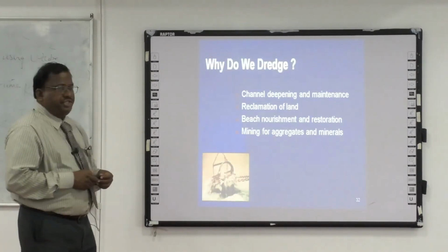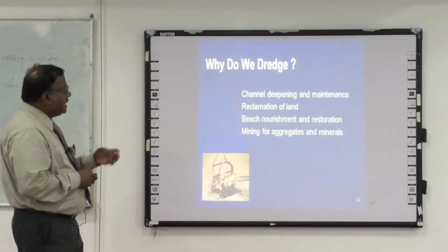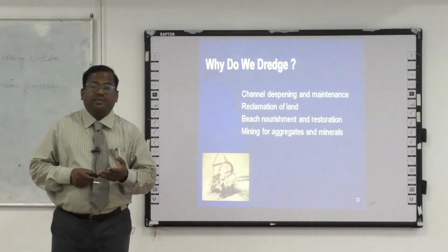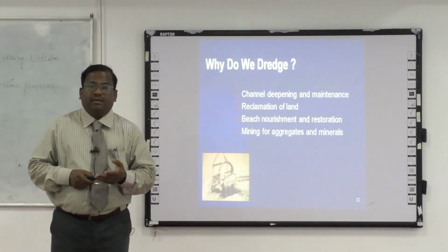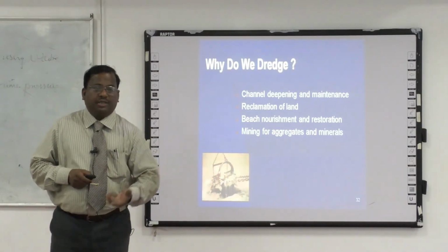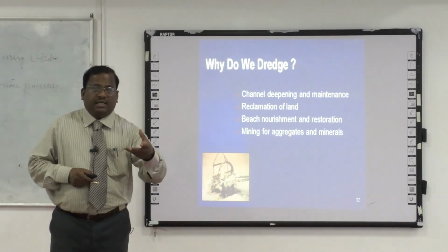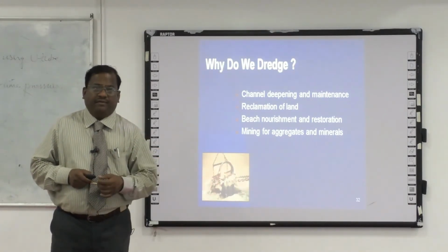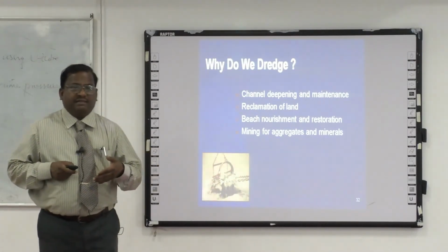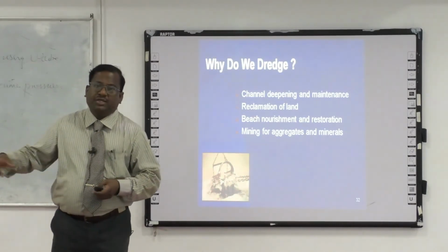So why do we dredge? What is the purpose of the dredging? Channel deepening and maintenance, which is a very important aspect in port development. When we develop a port, depending upon the location, the seabed depth will differ. So in order to make a convenient way for vessels to approach from the ocean into the harbor, the navigation channel is to be dredged.